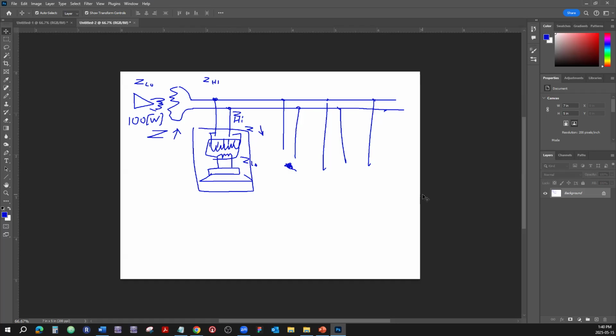Now, the secret of the trade is that I remember when you have the PA system at school, high schools, elementary schools, and you have those classroom speakers with the push button to make a call to the main office. And also there will be hallway speakers, just speakers in the ceiling. Same things with the transformer, except the classroom station has another circuitry which is connected to the push button in the class. So if you tap all the classroom speakers at 1/4 watt, and if you tap all the hallway speakers at 1 watt, then you're going to have a proper balance of volumes when an all call is being made. Because in an all call, all the speakers turn on, classroom speakers and all the hallway speakers.